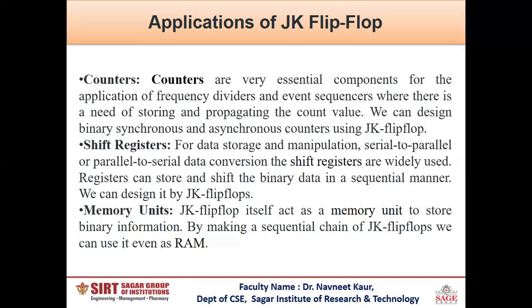Now, JK flip-flops are also used in shift registers. Registers are used to store binary information. A register is made up of flip-flops, where each flip-flop is used to store a single bit of information. So registers can be designed by using JK flip-flops.